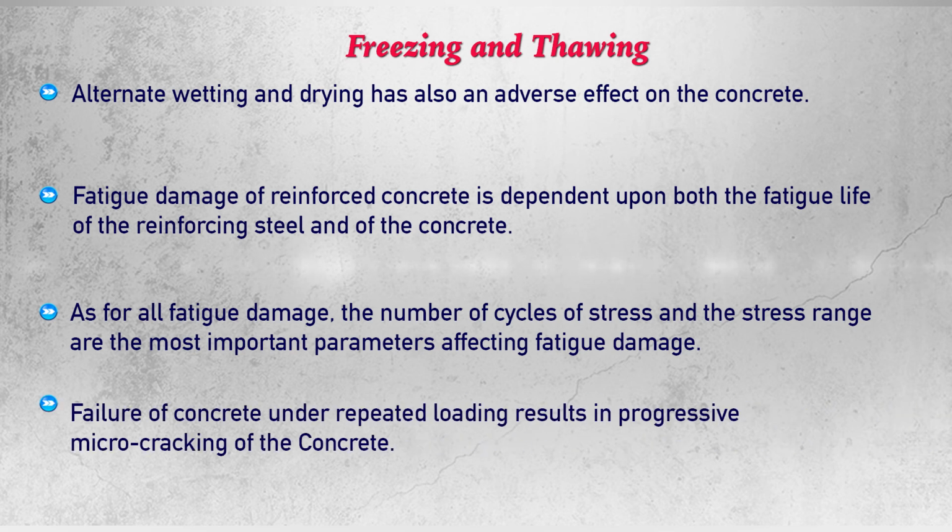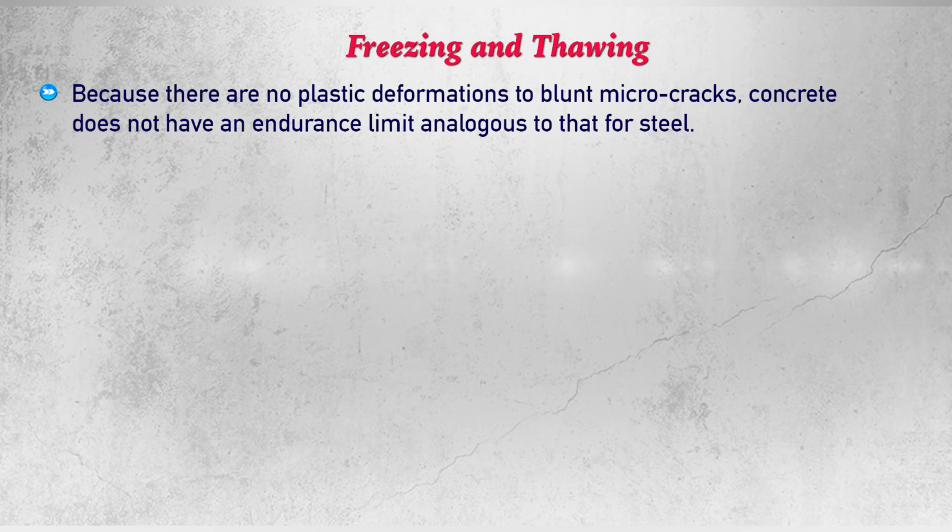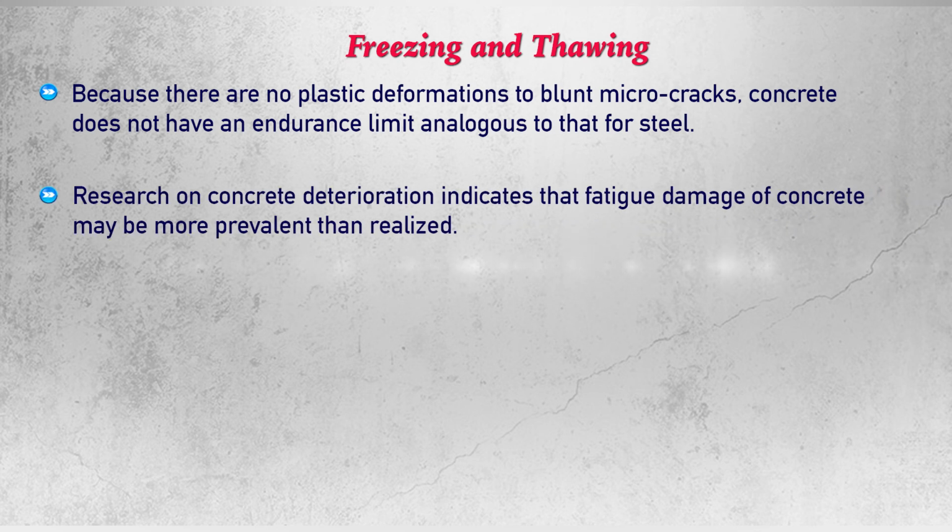Failure of concrete under repeated loading results in progressive microcracking of concrete. Because there are no plastic deformations to blunt microcracks, concrete does not have an endurance limit analogous to that for steel. Research on concrete deterioration indicates that fatigue damage of concrete may be more prevalent than it is realized.